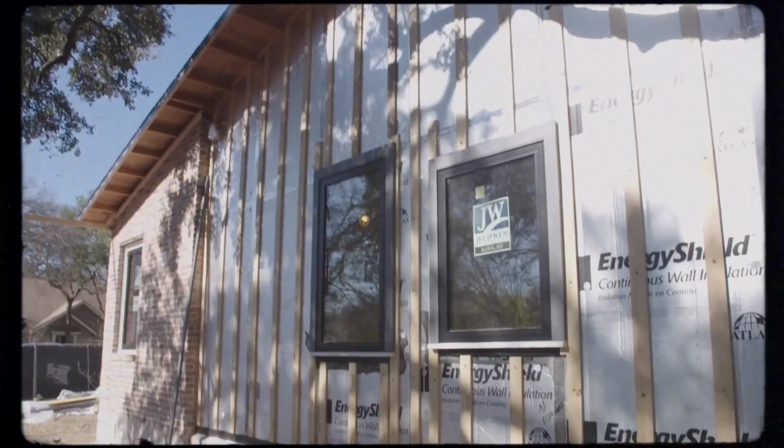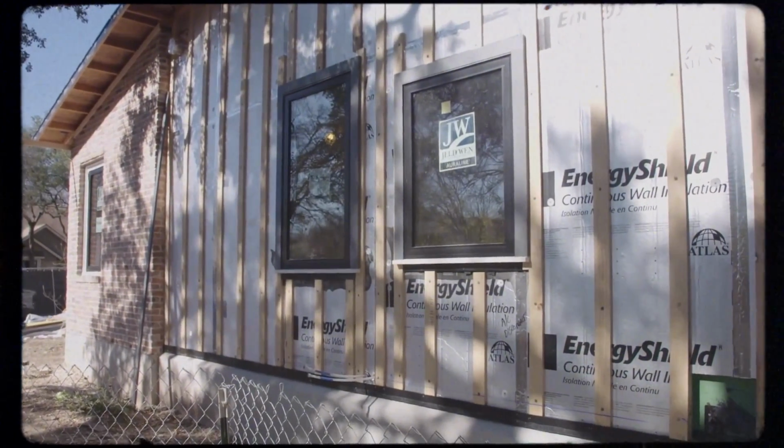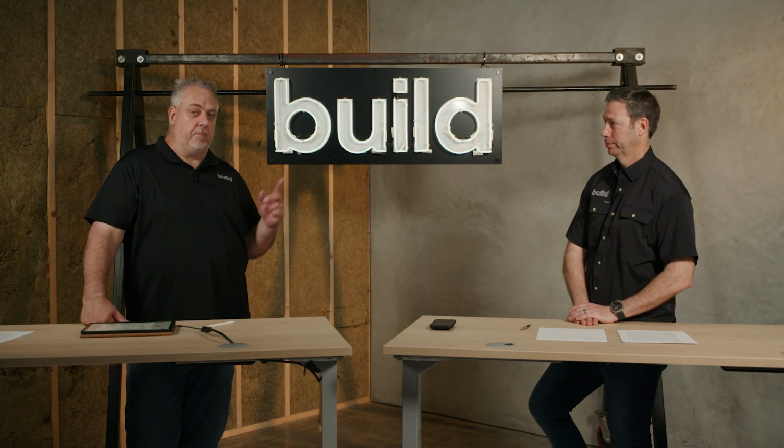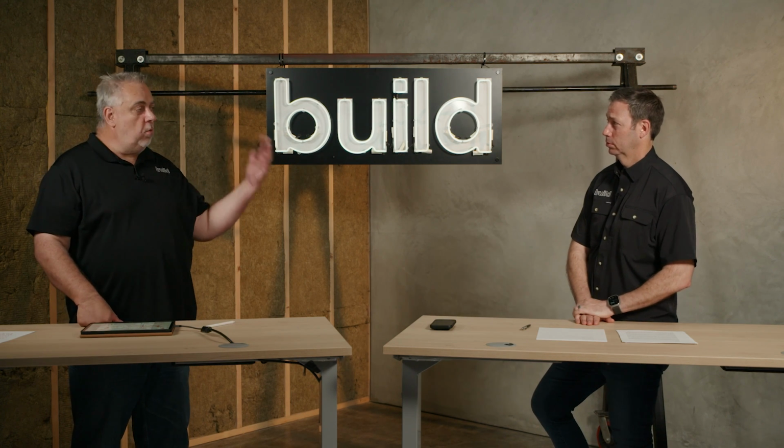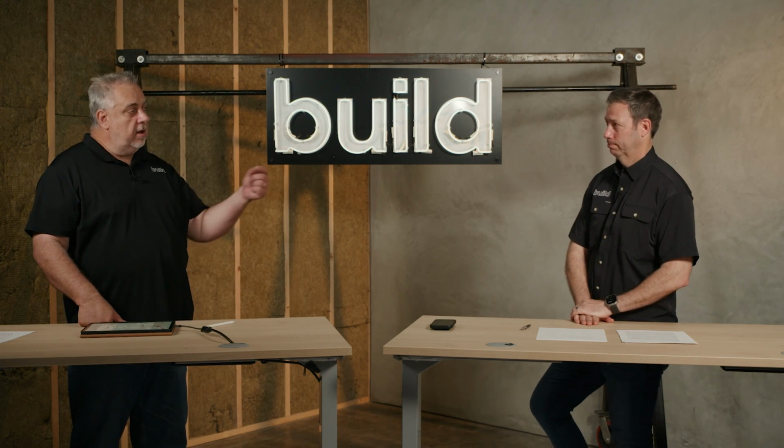I'm going to give you a little story, a little primer on that, something to think about. If I built a wall with a window and I sprayed water on it, that wall is going to get significantly challenged. The window is going to get significantly challenged. If I build a secondary wall and I put it 4 inches in front of that and I spray it, that inside wall is going to see 1/100th of the water that it saw when it was fully exposed.